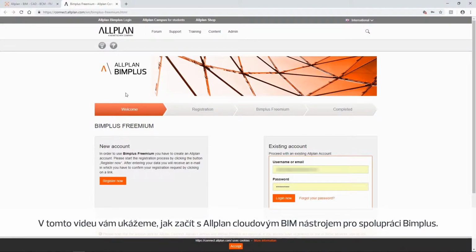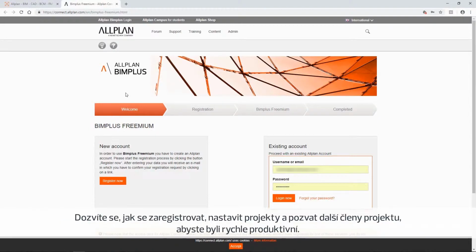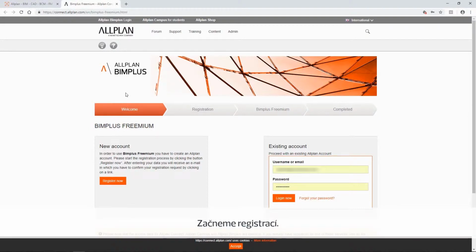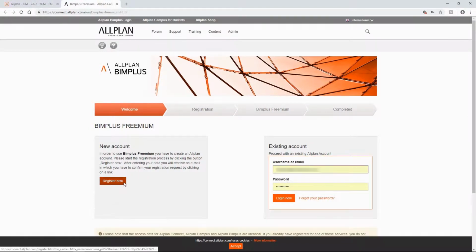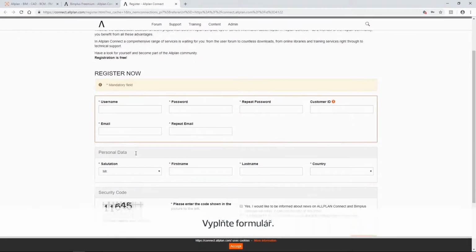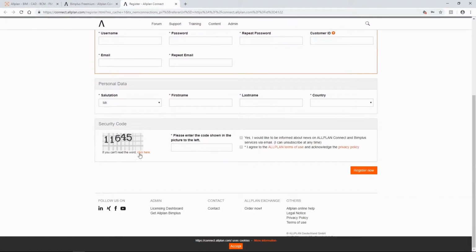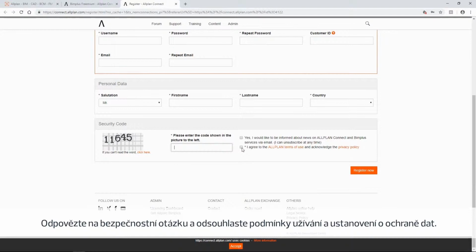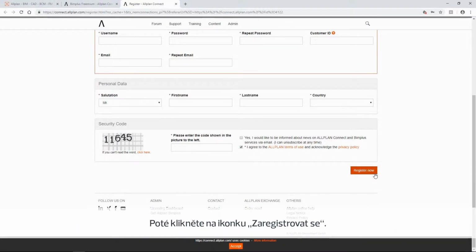In this video, we will show you how to get started with Allplan's cloud-based BIM collaboration tool, Bimplus. Here you will learn how to register, set up projects and invite other project members in order to get you productive as quickly as possible. We start with the registration. Click on the Register Now button. Now fill in the form. Answer the security question and agree to the terms of use and privacy policy. Then click on Register Now.